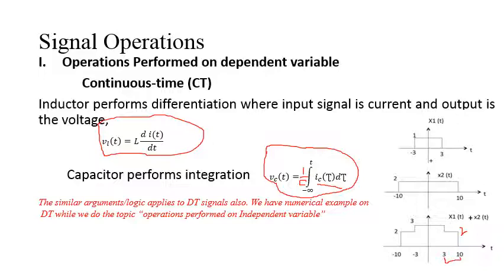Similar is the case for multiplication when we multiply two signals: like here we did point by point addition, there we will do point by point multiplication. A simple example is the AM radio system, in which we have two signals, the audio signal that you want to transmit and the carrier signal. We multiply the two signals point by point.